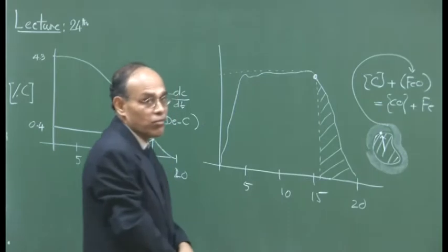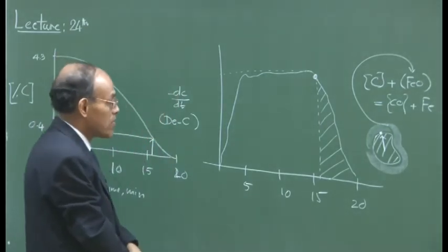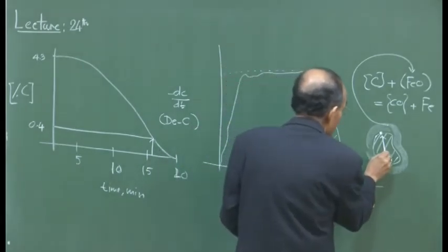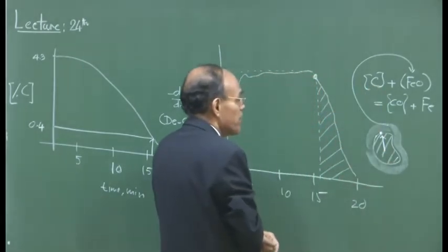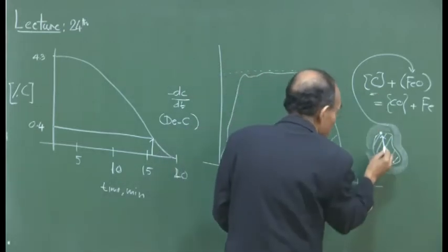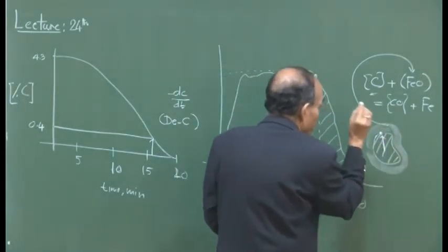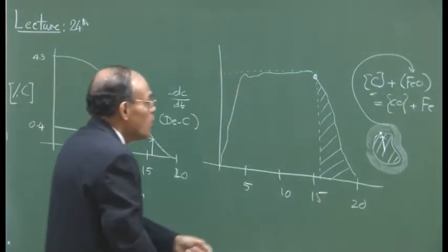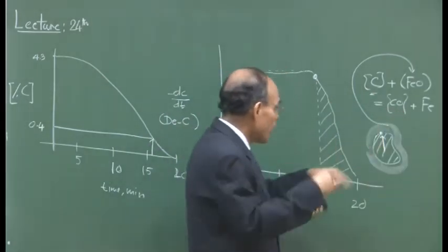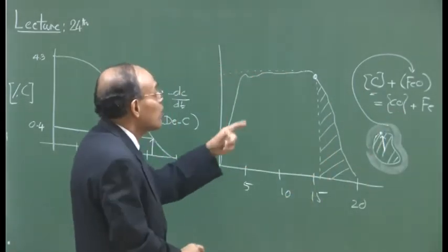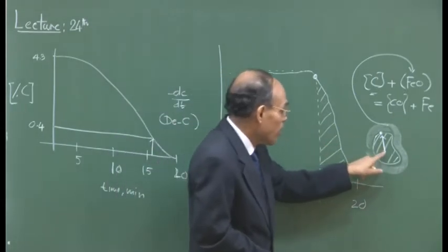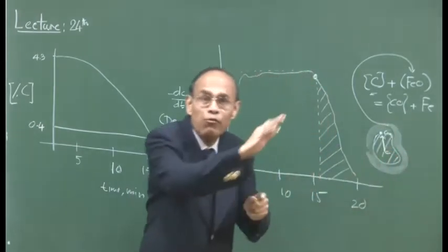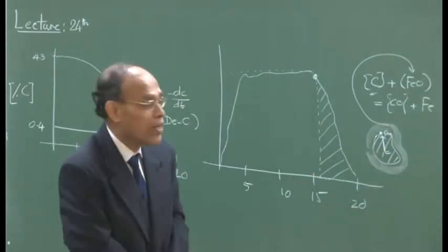This is the slag part, not pure FeO though, okay, we must understand slag is a mixture of many other oxides, and carbon is dissolved here, which of course does not have unit activity. So, it is not pure carbon, we are talking about dissolved carbon. So, the carbon migrates, and then FeO and carbon react at the interface, and so the chemical reaction is at equilibrium. So, virtually we can say that there is an equilibrium concentration, and the difference between the bulk concentration and the equilibrium concentration is basically the driving force for carbon to get transported to the reaction interface.